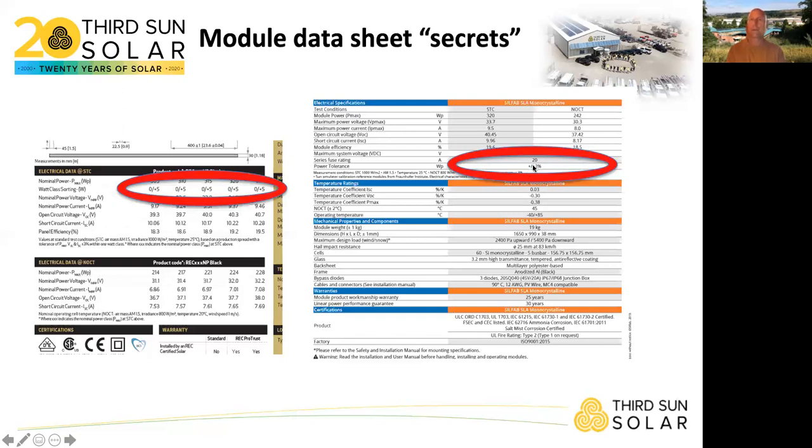For the most part, companies that have a positive power tolerance are higher quality, and they're focused on accuracy and details, and you're going to get something in the middle. We've actually tested many of the modules we get from this supplier, and they come in right in the middle. So the 300-watt module is probably going to be about 302 or 303. We haven't been purchasing these, but our third-party laboratories that are testing these are finding that consistently they're on the lower side. It's very rare that when you pay for a 300-watt module you get 300 watts. So again, one of the important things to look at is power tolerance.